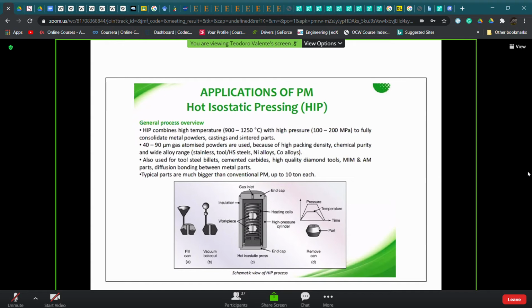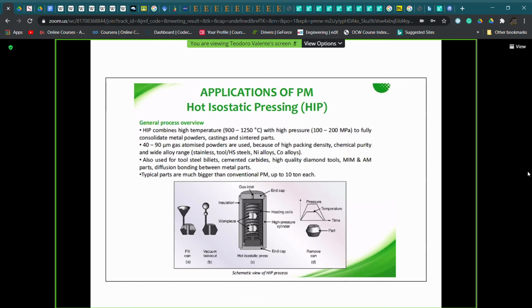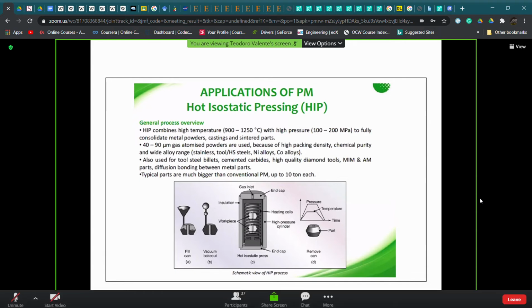for the fabrication of bulk ceramic parts, starting from powders and then consolidating these powders up to the green body by sintering, in which a thermomechanical cycle is applied. So we apply at the same time high pressure, with very significant values, higher than 100 megapascal.